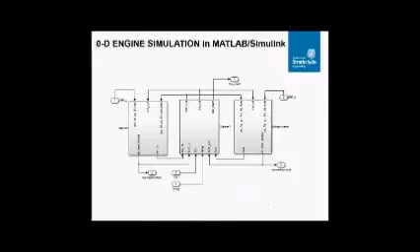In this slide is shown the part of the cylinder block representing cylinder number 1, including the scavenging ports and the exhaust valve. The engine cylinder is subdivided into 3 zones: a zone of pure air, a zone of combustion products, and a zone comprising air and exhaust gas.